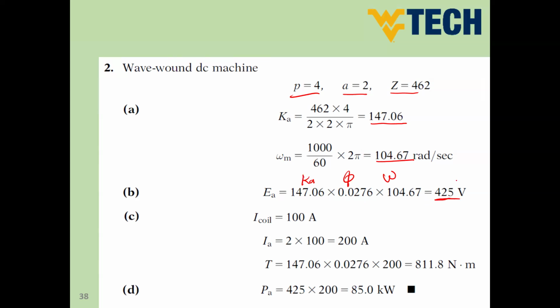So the volt is 2 times the volt that we have before, because we connected 2 coils in series instead of having 4 parallel paths. So we have now 2 parallel paths and 2 series connected coils. So this means, guys, here we have twice the voltage that we had before. What would be the current of the conductor? The current of the coil would be the same all of the time because the coil has a certain impedance and cannot support different value of current. So the current is 100 ampere per coil all of the time.